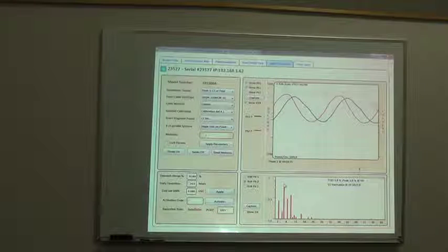But you can't go buy a harmonic filter, and correct me if I'm wrong, for the 5th order, for the 7th order, for the 11th. Well, those are all individual filters. How many of them are you going to put in there? Keep it in mind, every harmonic filter has its own losses. We talked about that.